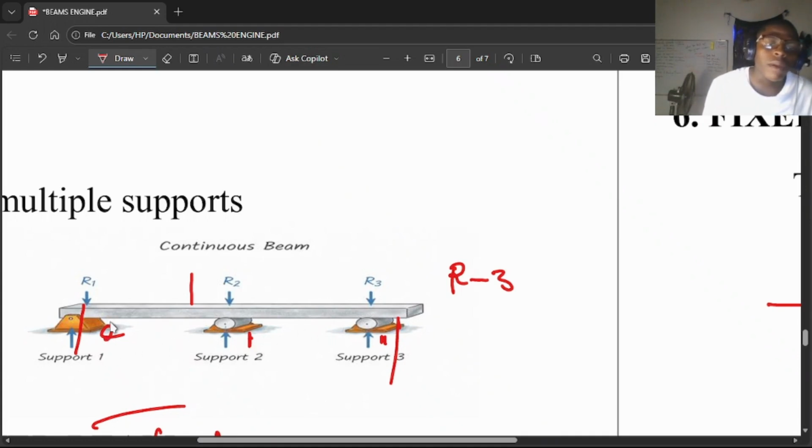But the two came about us knowing that this is a hinge support. So we basically have 2 plus 1 is 3, plus 1 again, that's 4. So we can see that your R is 4 minus 3. And what's 4 minus 3? This is actually 1.